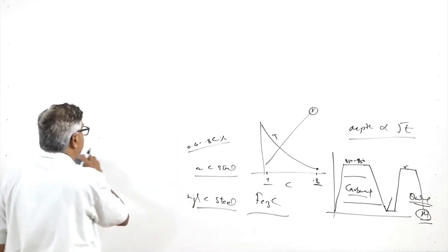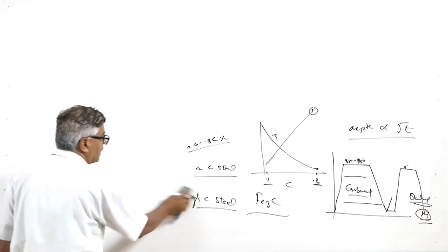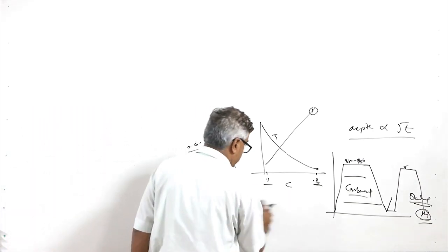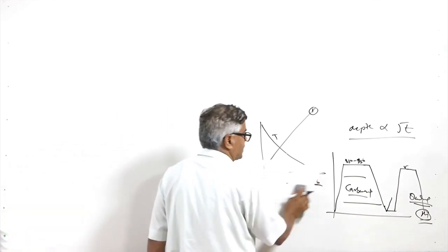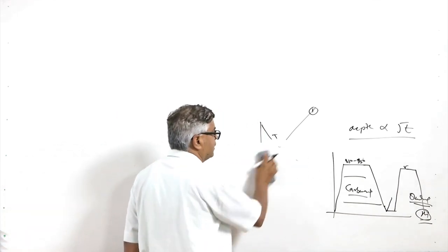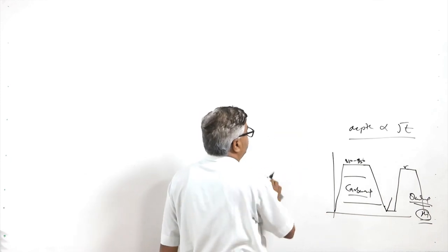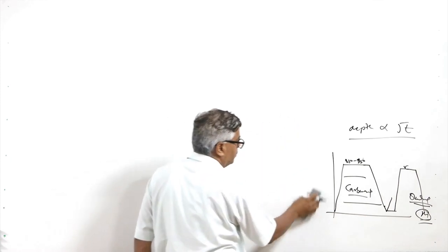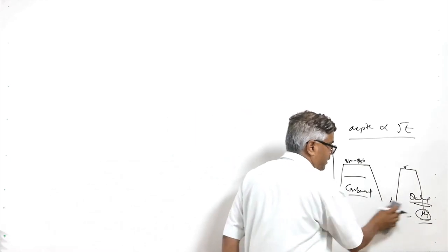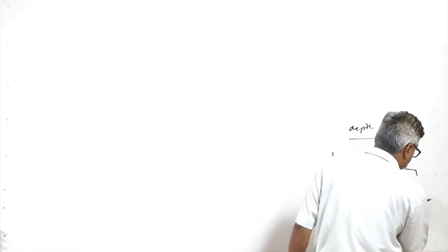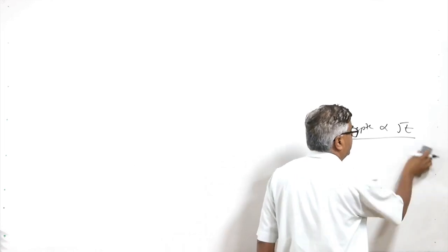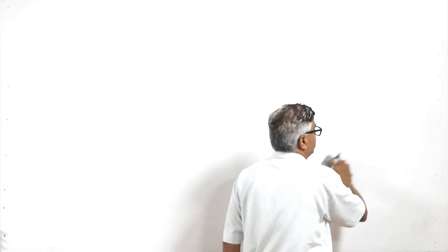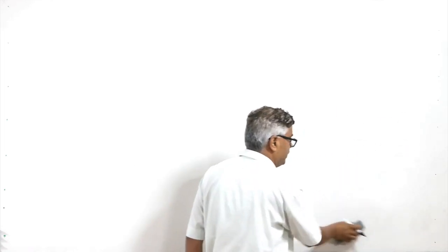We know that the carburizing is a diffusion based mechanism, wherein the diffusion is found a function of the temperature as well as time. So higher is the temperature, greater will be the rate of diffusion, greater will be the depth up to which carbon will be introduced in the modified surface or carburized surface. Similarly, greater is the carburizing time, greater will be the depth up to which carbon will be enriched.